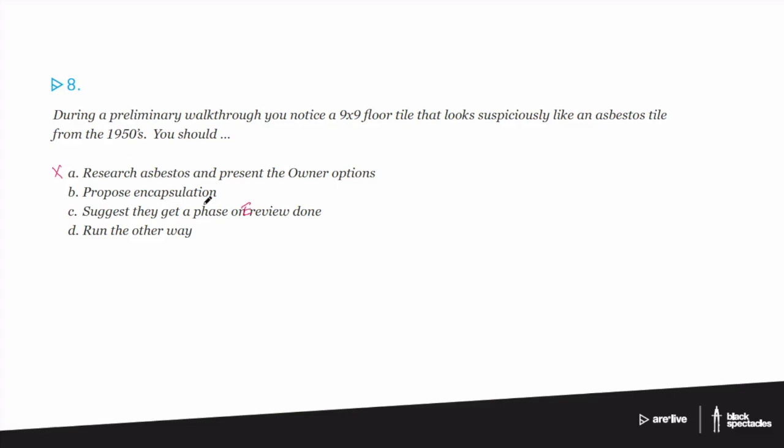Propose encapsulation. Encapsulating a 9x9 floor tile, putting a new flooring over the top, that's actually probably a great idea. It happens all the time. It seems weird to leave asbestos in a building, but if you think about the idea that you're going to remove all of that asbestos, you're going to break it all up and you're going to pull it out and